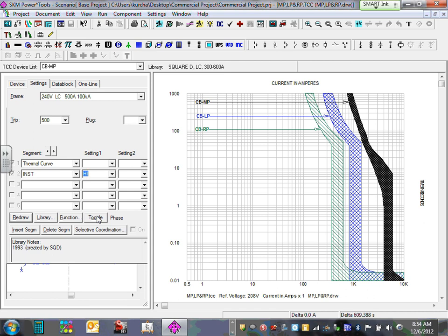Here's my problem, guys. Every time you mess with the instantaneous, you expose your panel to more arc flash, arc blast. So yes, it's better coordination, but now you're exposing the electricians who are working in this area to a higher arc flash for a longer time. Who cares if you're wearing the PPE? So long story short, you're going to have the heavy medium.